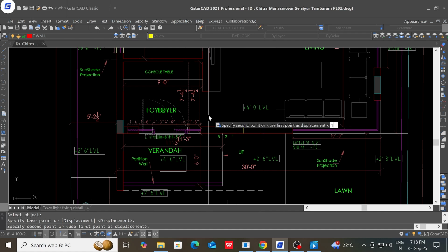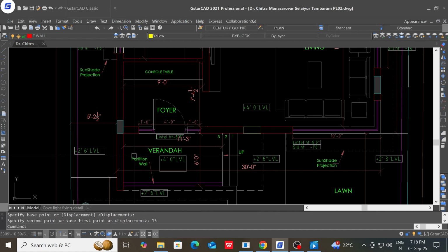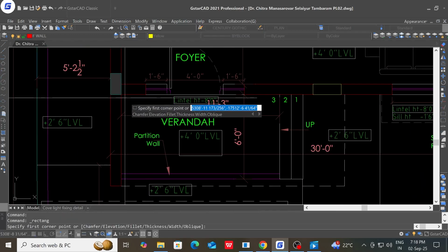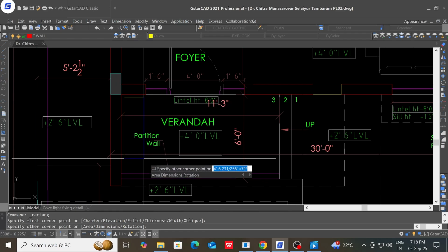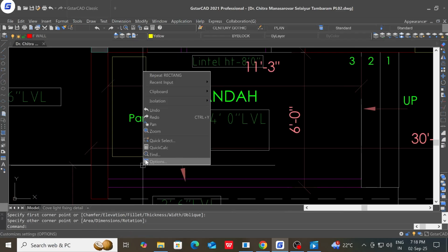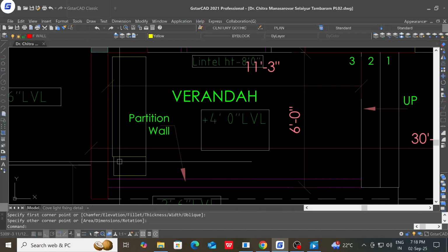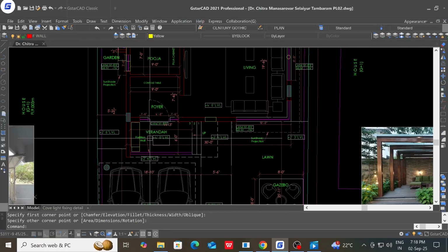Try to bring this door towards this side, so that there is another advantage in doing this. When I bring this, what do you get here? Yeah, the space for the shoe rack. So this is one thing. We should have a shoe rack on the outside, accessible from the outside. Whatever you bring, put inside, people will not use the inside space. So you should have a shoe rack along with a small seating attached to it for removing your shoes and changing your shoes, wearing your shoes. This is very important. In each and every house we should address this.